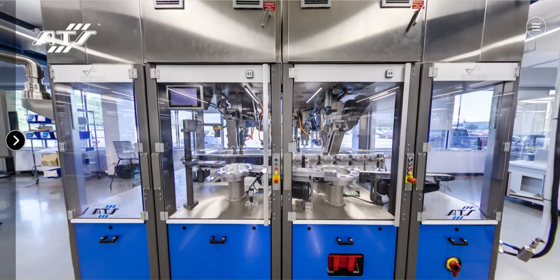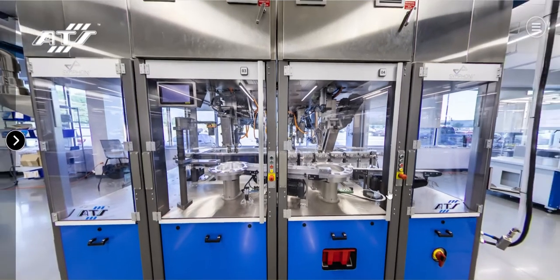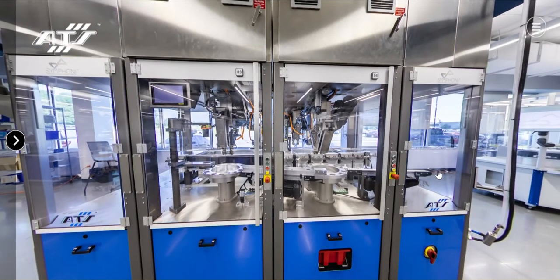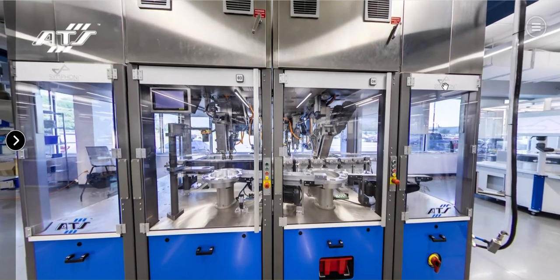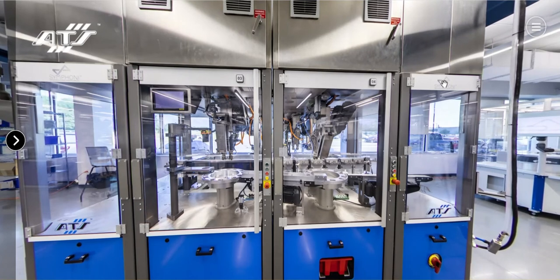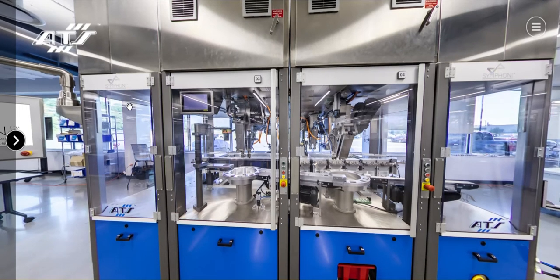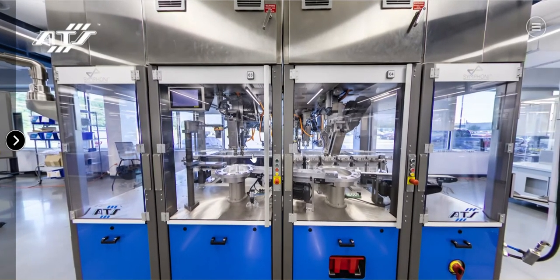And then there's also two end modules, or what we sometimes refer to as end caps, bookending the system, so to speak, where on one end we have an end cap that serves to receive main power distribution, and handles all of that distribution of power and air through the system. And then the other end cap is used to house the PLCs and associated electronics for controlling the SuperTrack pallet transfer system, which is at the basis of the Symphony technology.